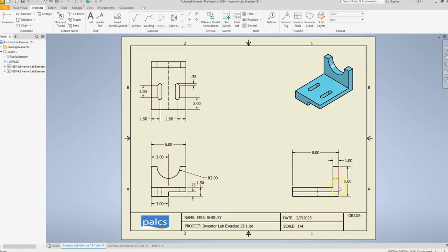And then coming up here, it shows 5, but it's not 5 because we have this little piece over here that we have to subtract off. So this is going to actually be 4.25. We will come over 1, and then we will come down 3.50, and the way we get that number is we are taking the 5 minus 1.50, which gives us 3.50. We're going to come over and we're just going to finish it off, and that's 7, and then we will just close it off.